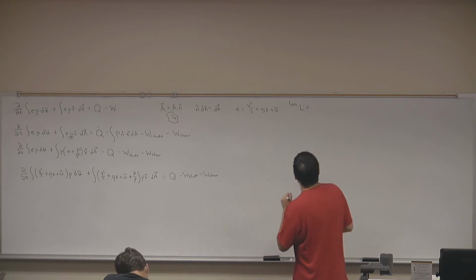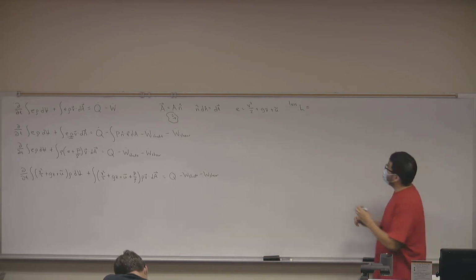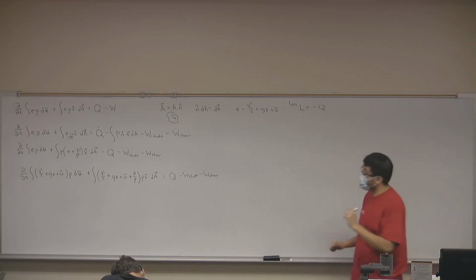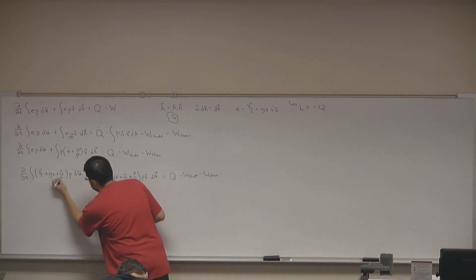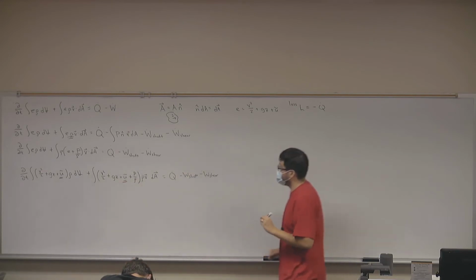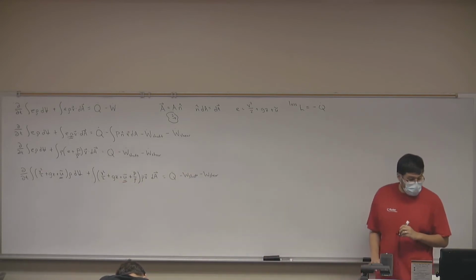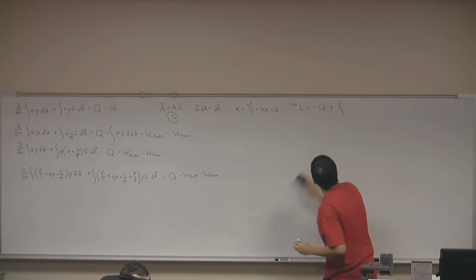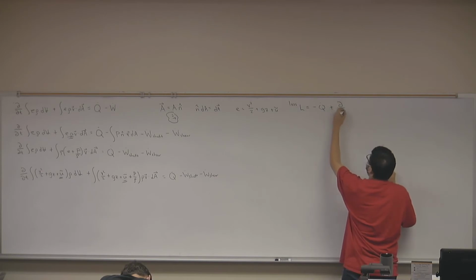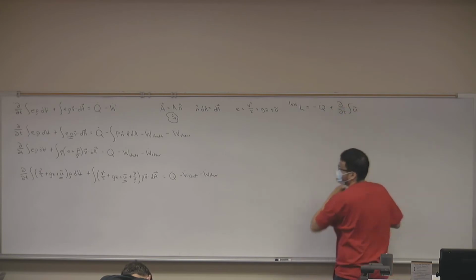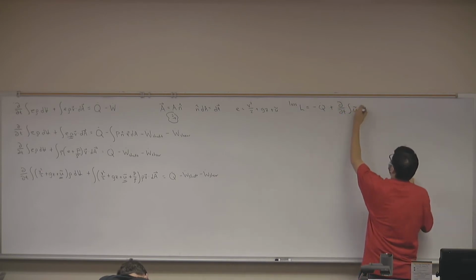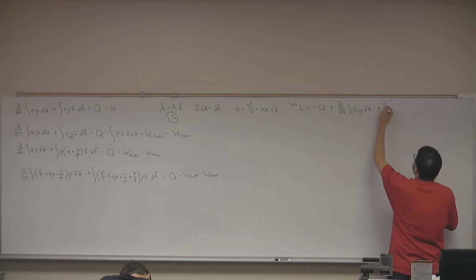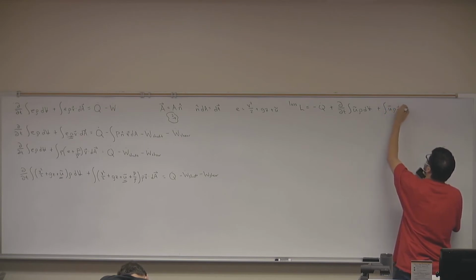So I'm going to define this loss as my heat transfer rate and, like Jet said, my internal energy. In other words, these terms. So I get that my loss is equal to the heat transfer rate, the partial change with respect to time of my internal energy, rho dV, and the flux of my internal energy. Good.